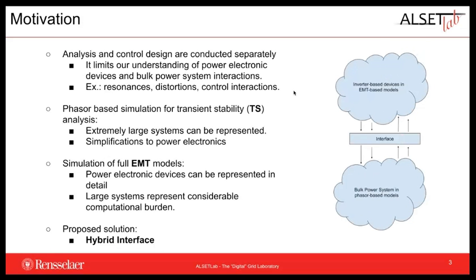Hence, the analysis and control design of different systems is conducted separately, not allowing us to observe interesting and important phenomena such as resonances, distortions, maybe even control interactions. For example, phasor-based models will require oversimplification of power electronic devices, while EMT models are too detailed for the representation of large systems.